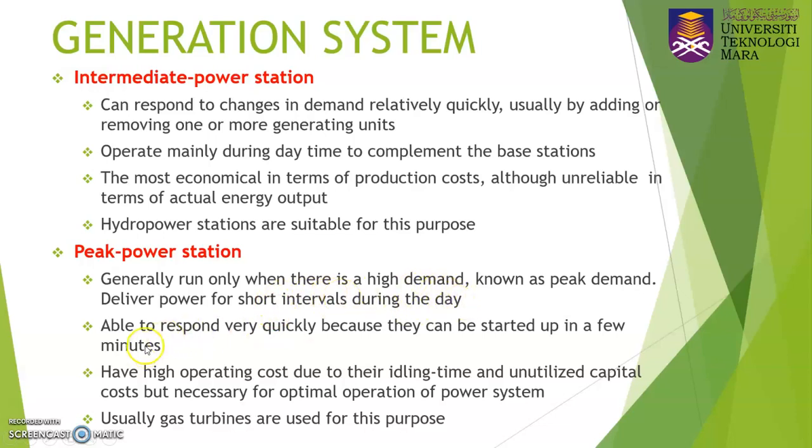The peak power station also must be able to respond very quickly and can be started up in only a few minutes. Peak power stations also have high operating costs due to their idling time and unutilized capital costs, but they are necessary for optimal operation of the power system. For example, we can use a gas turbine as a peak power station.